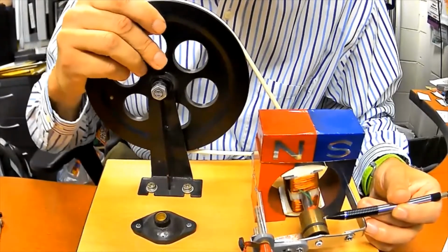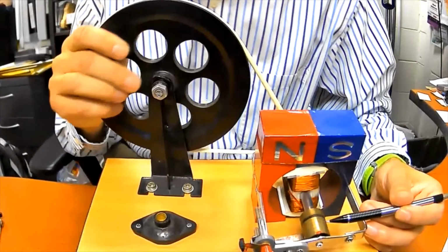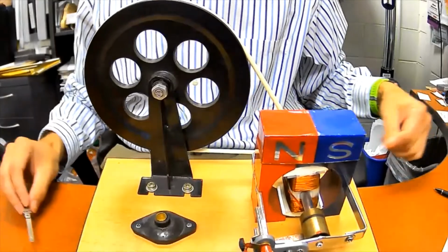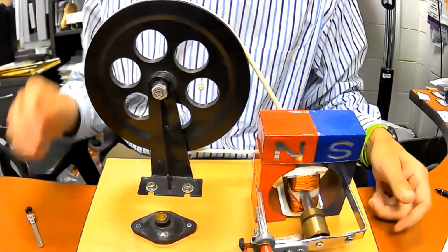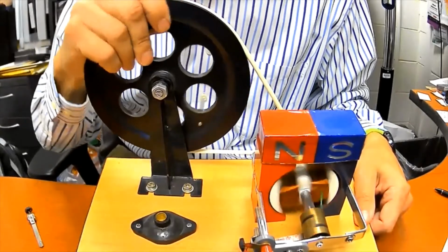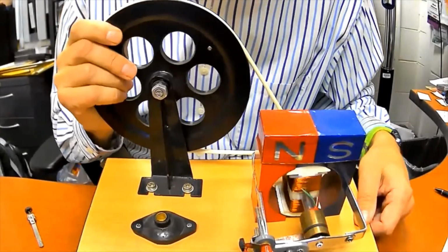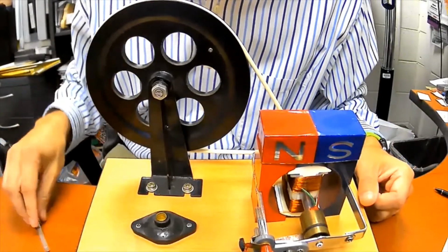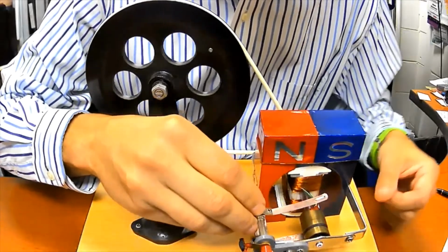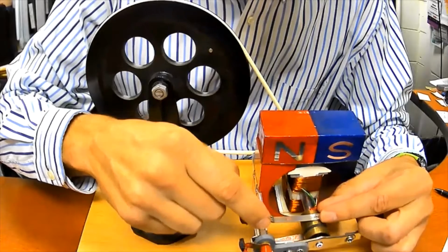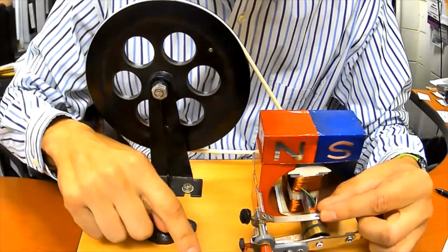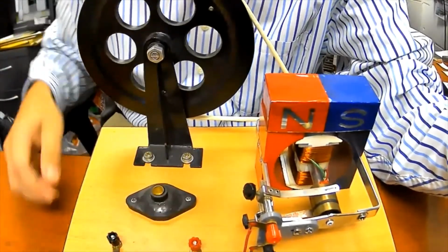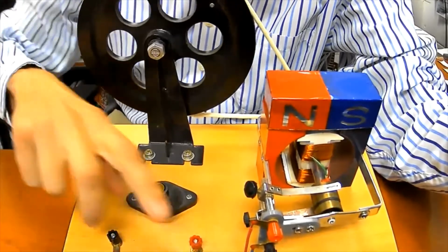You don't see that with larger machines just because larger machines are designed specifically to be either AC generators or DC generators. But this little hand crank generator, it's pretty cool that it can function as either an AC generator or a DC generator, basically by changing whether this functions as a set of slip rings or a split ring commutator. All right, and then the brushes are connected to this rod right here, and that's connected to this wire, and so then here are the outputs from the machine. Whether it's an AC generator or a DC generator, either way, you take the output from here.